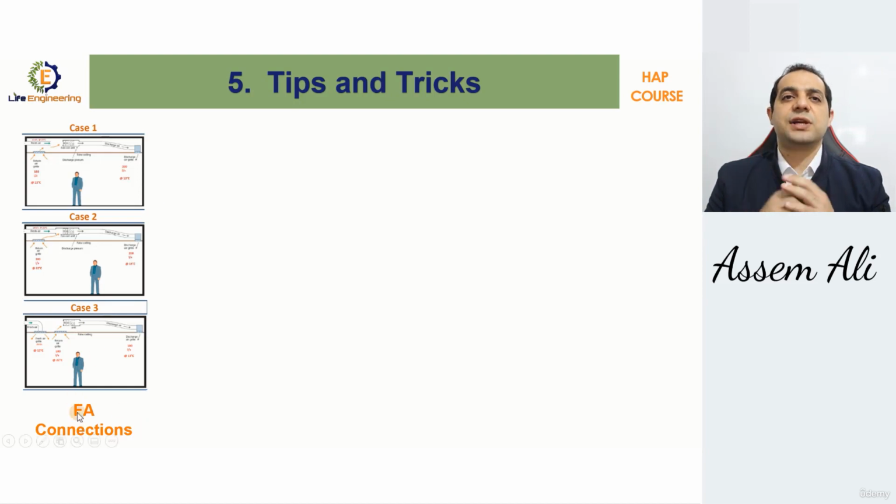One example is related to the fresh air connections. What's the proper type of connections? Free above the false ceiling, direct to the fan coil unit plenum, or direct to the space itself? What is the proper temperature for each case? How to perform air balance in each case? Which one should we use in the design and why? How can the information be added to the HAP, either for the supplying FAHU or for the receiving FCU or AHU? This is one example.